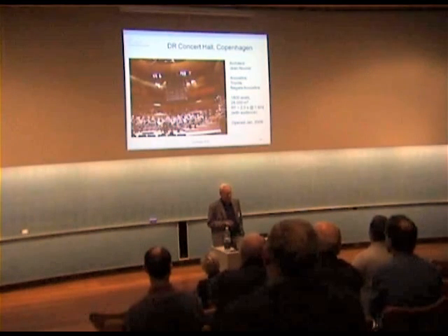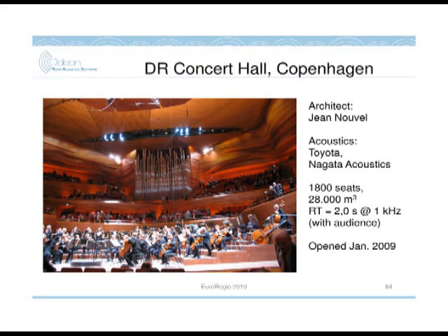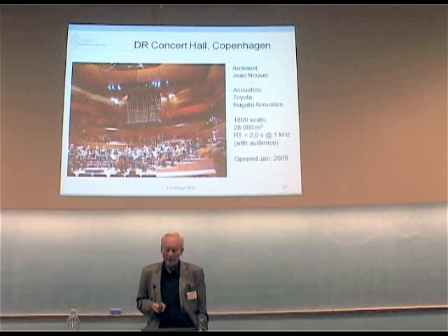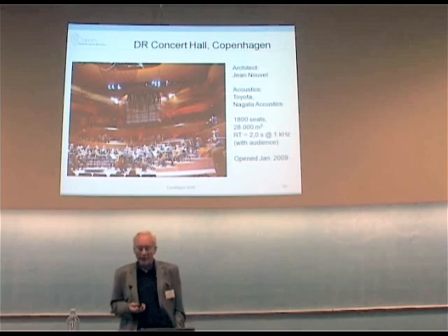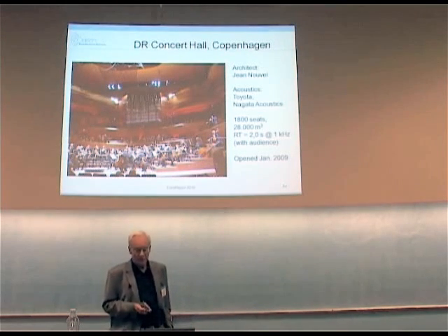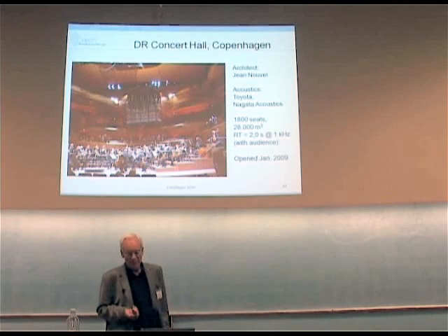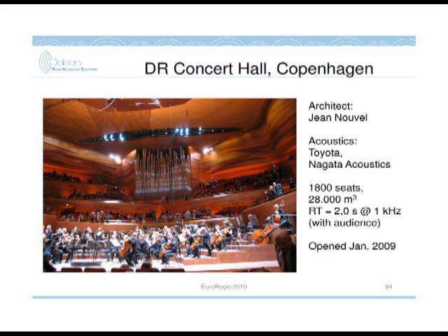What I should like to use as my example here is the new concert hall in Copenhagen, designed by Jean Nouvel, with Nagata Acoustics as responsible for the room acoustics. You can see the data here: 1,800 seats, 28,000 cubic meters. Reverberation time with the audience about 2 seconds at 1 kilohertz.